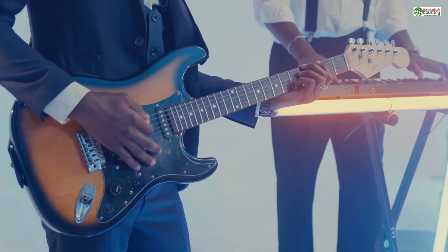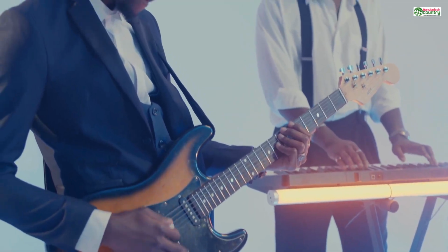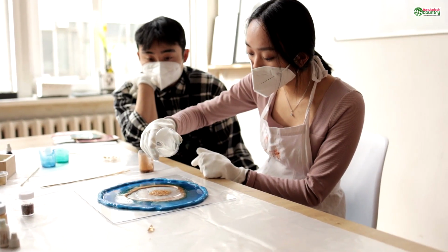For resin printers, which use UV light to cure liquid plastic, the problem is different but just as real. As the print builds, the model is pulled out of the resin vat. If a wall is too thin, that suction force can literally rip it apart or warp it like a wet piece of cardboard. Even if it survives the print, a paper-thin wall is too fragile to withstand the mandatory post-processing steps of being washed in alcohol and blasted with more UV light to fully cure.